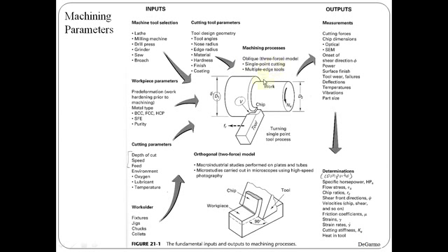The cutting parameters are properly set: the depth of cut, speed and feed, along with the working environment, with the use of coolant or lubricant, and oxygen and temperature effects may be considered during the operation. This process is supported with work holders, which may be fixtures, jigs and chucks, depending on the nature of the work part.